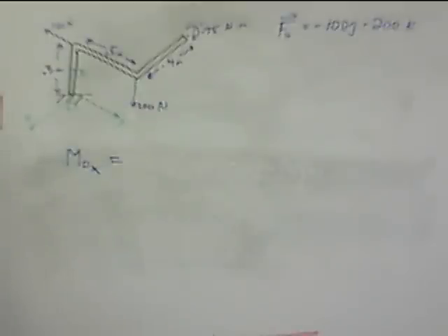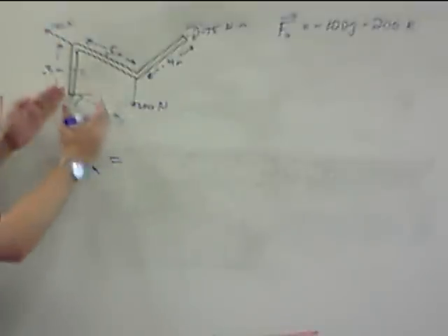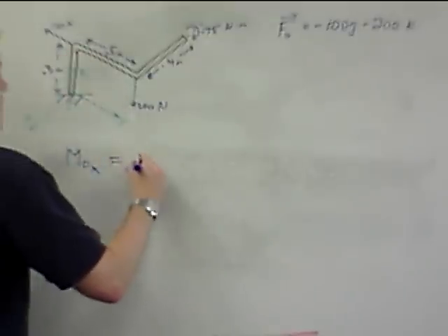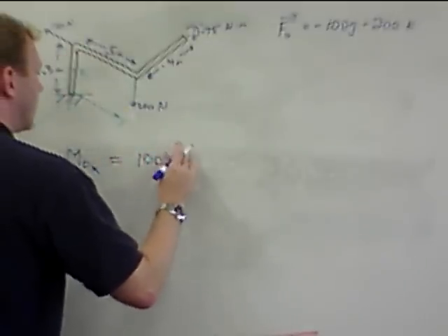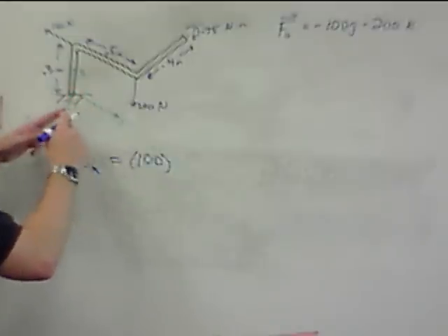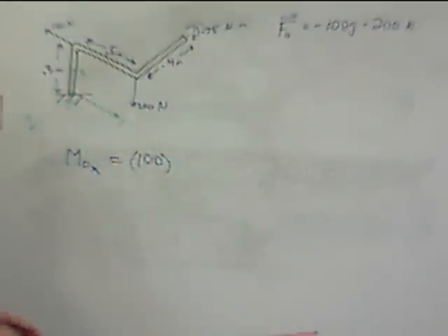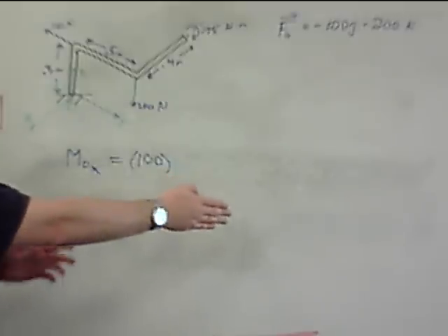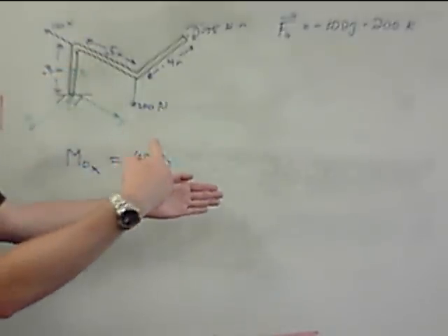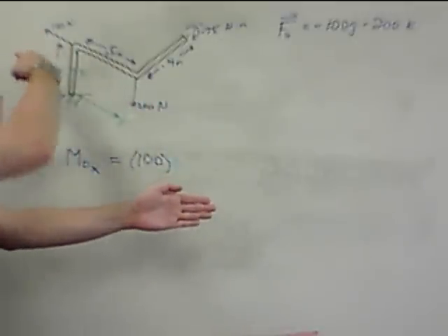All right. So this force, we have this fixture here on the x-axis. This thing's going to cause rotation this way. So we have 100 newtons, I'll leave the units out for now, times the perpendicular distance. This is where it gets tricky. We have an x-axis, and the force is being applied in the negative y direction, so that is perpendicular.